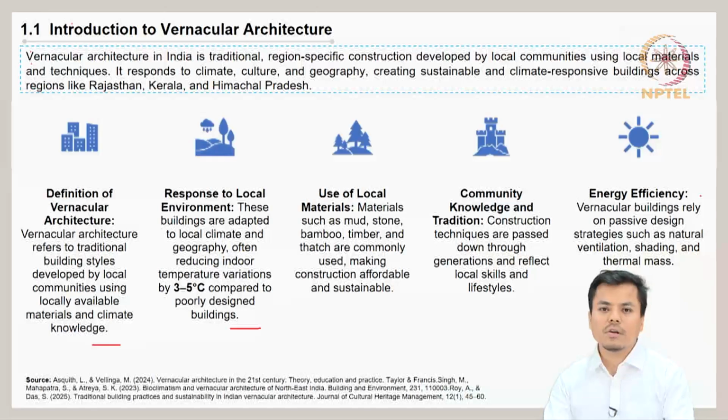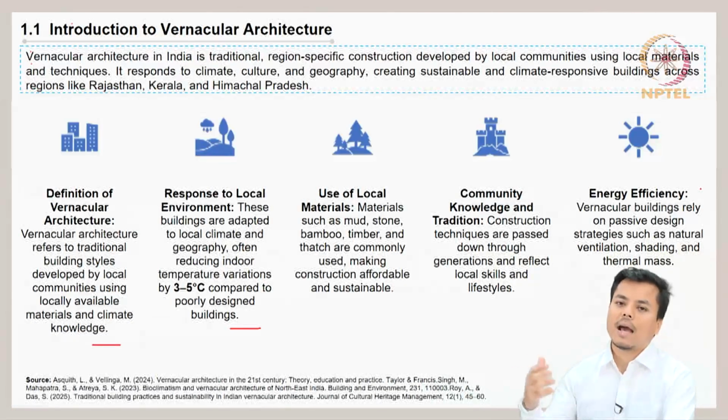So the houses were designed in such a way that, with respect to the local vernacular architectural style, the climate was in focus. Based on that, the amount of light that has to enter and the ventilation that has to be allowed were all specifically considered in designing the openings and the overall building as a whole. Since there was no electricity in that region, one had to depend on natural light and the natural flow of air.